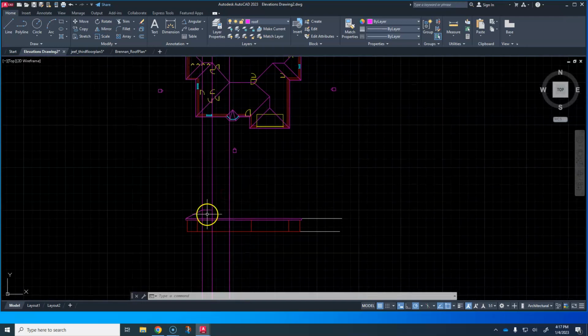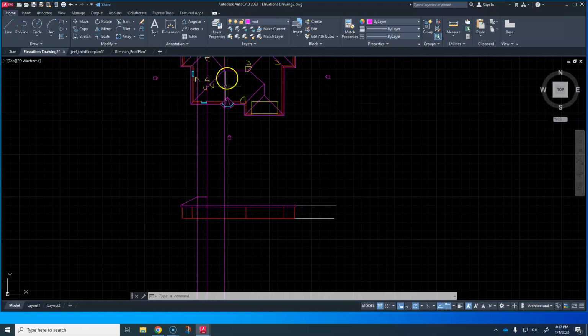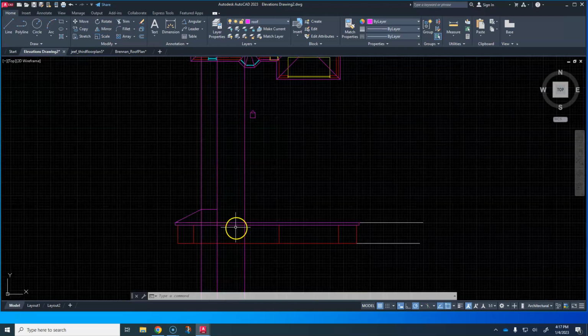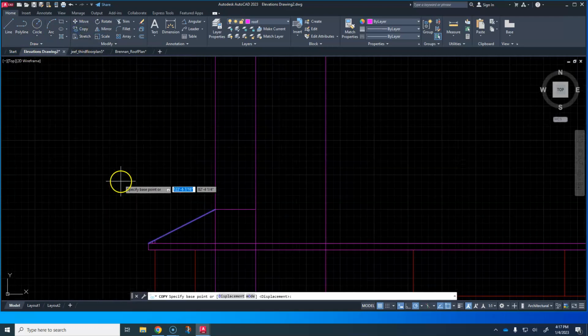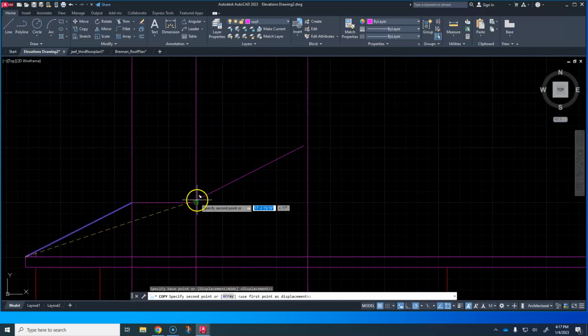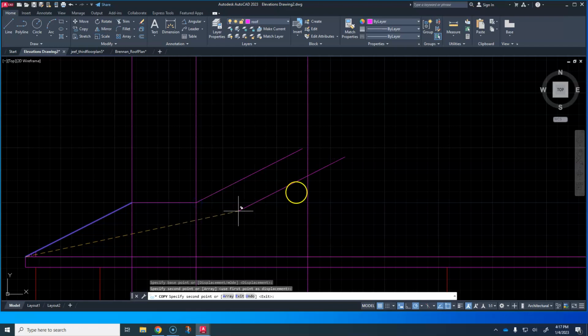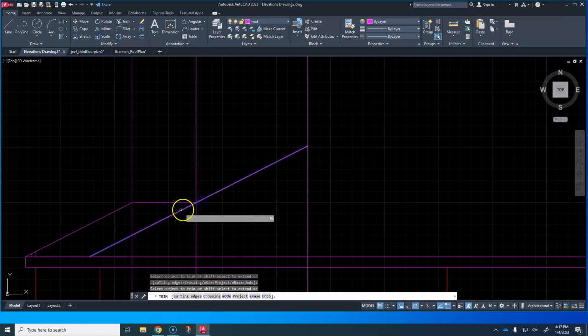All right. Now, here's where we need to get that same angle back, and we've got to go up to that ridge right there. But I'll show you a little shortcut. You can actually take this one, copy it. For a reference point, just use the very tip right there and then bring it right here. Drop it there and then hit the escape key. Then go to the trim tool and extend that by clicking on the shift button. You want to extend it down here too. It's got to go all the way to right there.